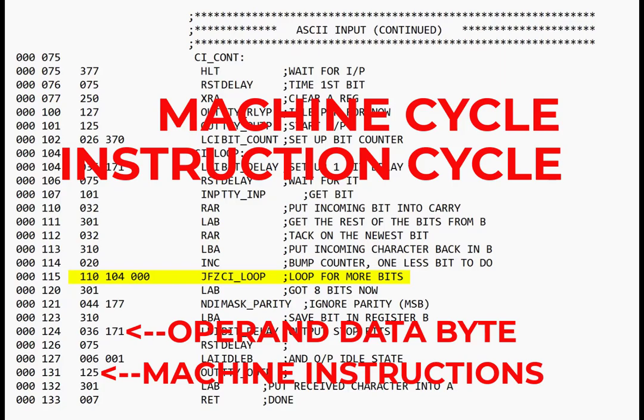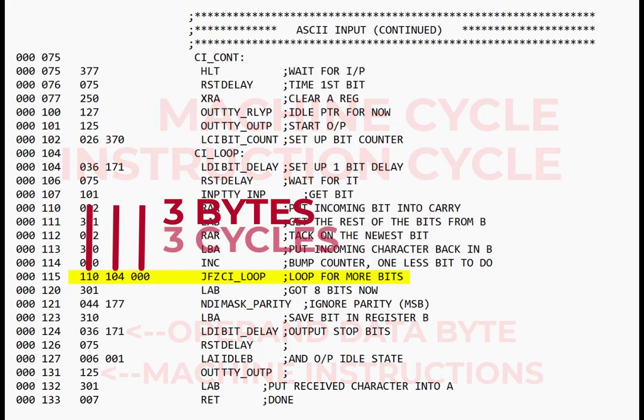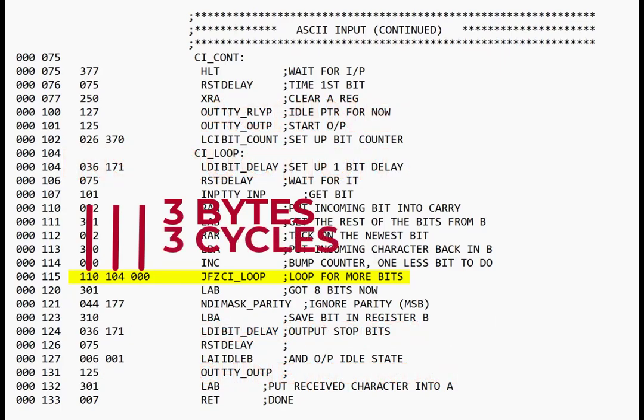For that time period, the processor is executing your instruction, meaning the whole time it's getting the machine instruction and any operand bytes and then executing that instruction. And that term obviously makes much more sense. And now if we've got a 3-byte instruction, the 8008 machine cycle is the fetching and executing of the instruction, but we know this is done sequentially, meaning the bytes are read in one at a time. So for a 3-byte instruction, that whole process would take 3 cycles, and that seems logical enough.